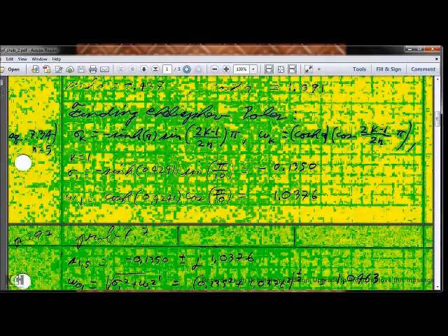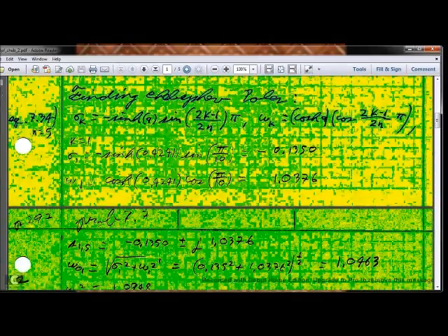So here's an equation for our Chebyshev poles from the book. Sigma k is negative sinh A, sine of 2k minus 1 over 2n times pi. Omega k, the imaginary part of the pole, is cosh A, cosine of 2k minus 1 over 2n times pi. We calculate sigma 1 and omega 1 here.